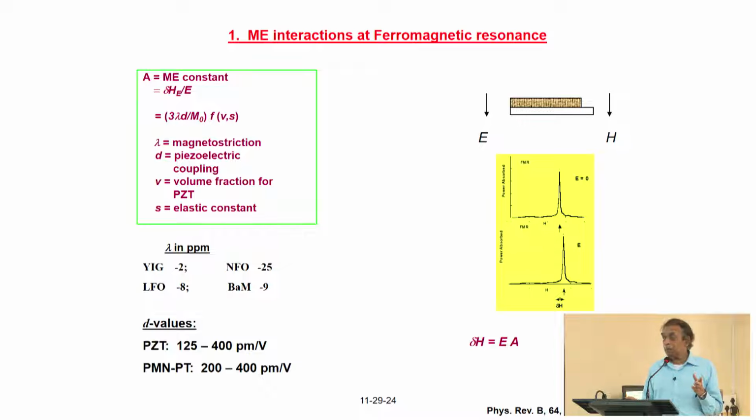It's not highly magnetostrictive, but the advantage is it has very small line width and very low high frequency losses. So, it is a preferred material for most of the applications for devices operating up to 12 gigahertz. When you go higher in frequency, the problem is that for any YIG device, you have to have a bias magnetic field to operate.